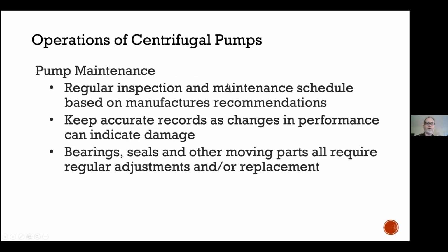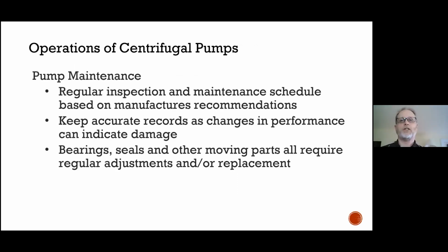No matter what type of centrifugal pump is installed, as an operator, it's really imperative that you learn what the manufacturer has recommended. Now you can go online and see the actual pump manufacturer, motor manufacturer, and download maintenance manuals. And if you don't, you should, so that you are on track with regular maintenance. It doesn't matter what the appurtenance is in a water system, regular inspection is critical, just so that you can document if there are any changes in performance.